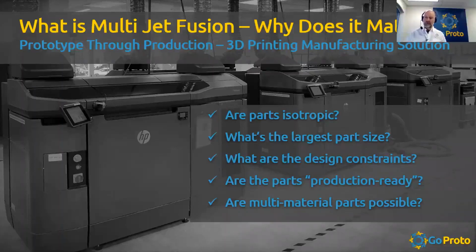It's important to know that there are no supports in this process. It is a powder bed technology, so the areas that are not fused, that are not part of the part, remain unfused, and they are surrounding the part to support it as it's built. So unlike other processes like stereolithography or digital light processing, or say additive powdered metal, that have supports that we have to mechanically remove afterward, this process results in parts that don't have supports. They just have powder that needs to be removed. So it's important to know that, because that affects some of the questions you all had about geometry, design constraints, and so on that we've got listed here.